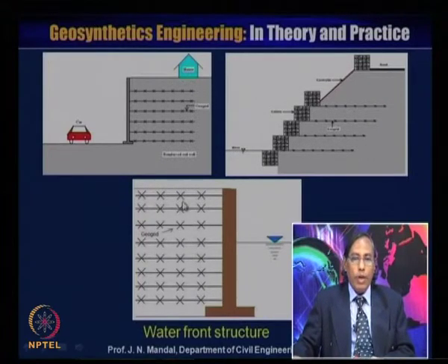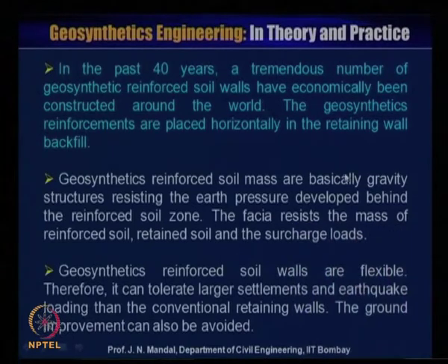In the case of a waterfront structure, you can see this is the water table, and then you can construct the reinforced soil wall, with a number of reinforcement layers. In the past 40 years, a tremendous number of geosynthetic reinforced soil walls have been economically constructed around the world. The geosynthetic reinforcements are placed horizontally in the retaining wall backfill.